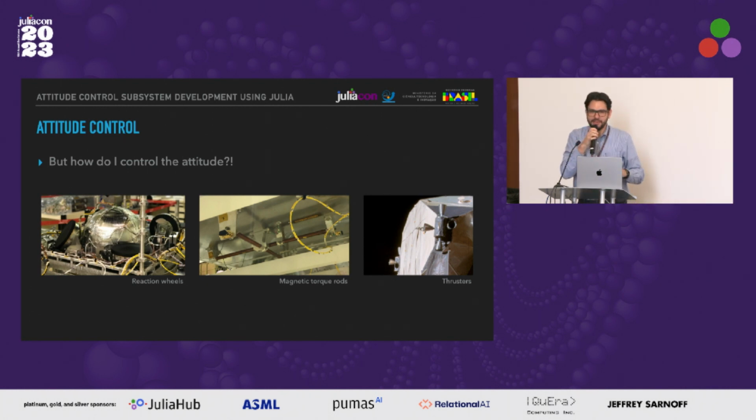This is a very nice question. We have two modes. The first one is entirely simulated. Then, for example, the reaction wheel is simulated inside the simulator, and we are communicating. And we have a second version where the reaction wheel is plugged into the computer. The computer commands the reaction wheel, reads the state of the reaction wheel, and sends its states to the simulator. Because, for example, for the dynamics, the system only needs to know the angular momentum in the reaction wheel. So if I get this from the computer telemetry, I can close the loop with the actuator in the loop or entirely simulate. We have these two modes. It's possible.